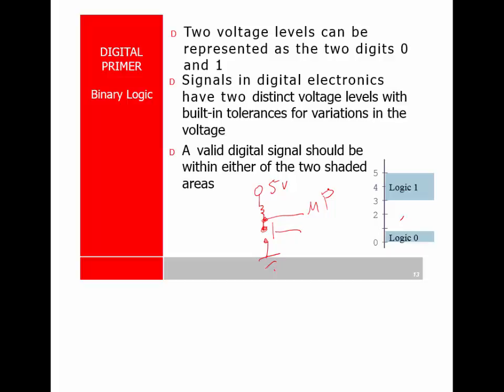None. It's an open circuit. But if I took the same circuit and I drew it this way, right here, and I push the button on that side there, and here's my input going into my microcontroller or microprocessor. When I push the button, I open the circuit. This would give me an active high out signal right there. This is active low right there.